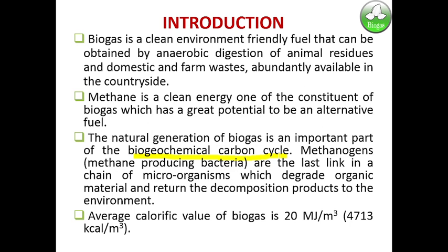Then with different feedstocks, to produce 500 grams of methane, you have to add 2 kg of feedstock. If you have 2 kilos of cow dung manure, then you can produce 500 grams of methane. That is one fourth, so to produce 500 grams of methane you have to add 2 kg of manure. You have to feed the slurry and make the slurry continuously to keep a continuous source for this biogas plant.